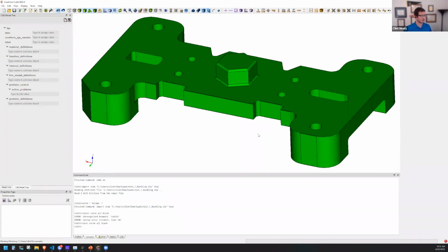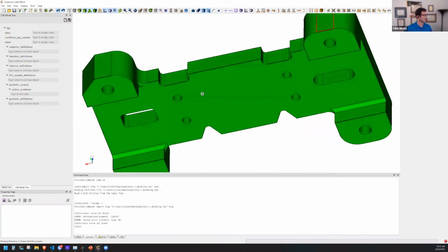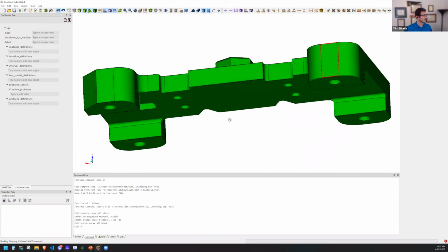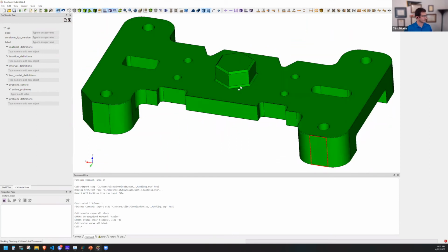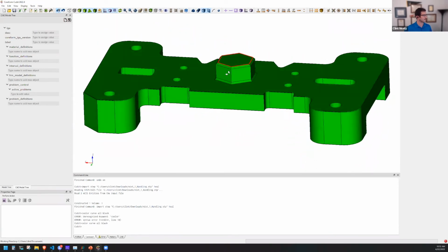So he decided to model it. Well, to an analyst, that is nightmare fuel, because in a traditional FEA we would now have to go in and simplify every single one of these rounds all around the perimeter of the top and the bottom. We would also then need to go in and fill in these other fillets at the base of this hexagon pedestal.